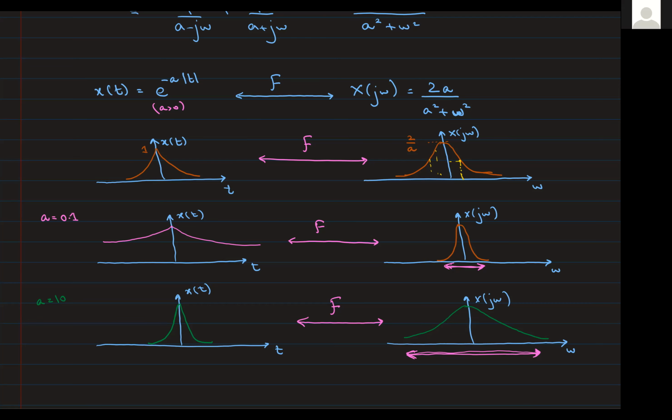But sir, it also depends on who spoke it. If someone with a shrill voice speaks, the transform would shift to the right side. It would shift to the right in the Fourier domain, not necessarily in the time domain. Sir, basically two same signals in the time domain are getting different Fourier transforms. No, there is a one-on-one relationship between the time domain and the Fourier domain. If you have two time domain signals which are different, then the Fourier domain would also be different. One-on-one relationship.